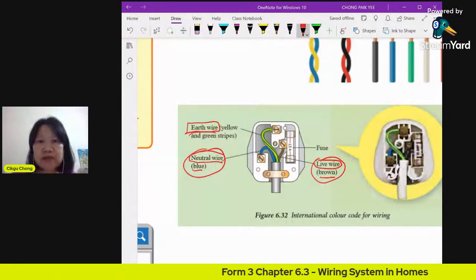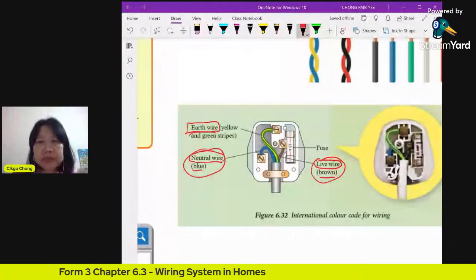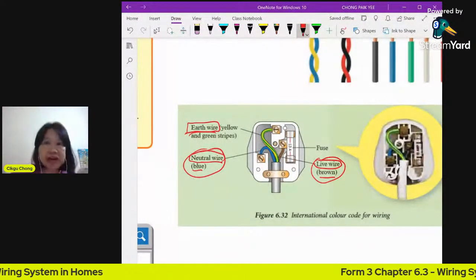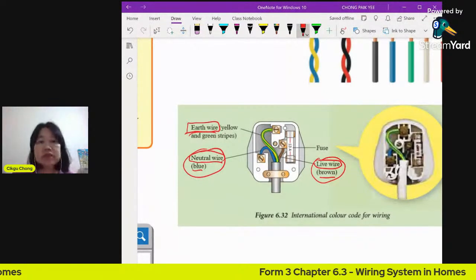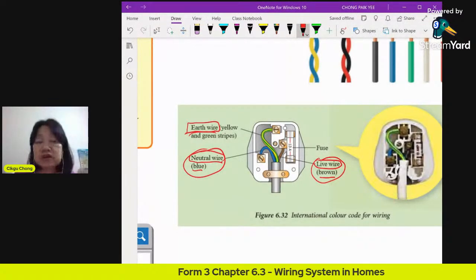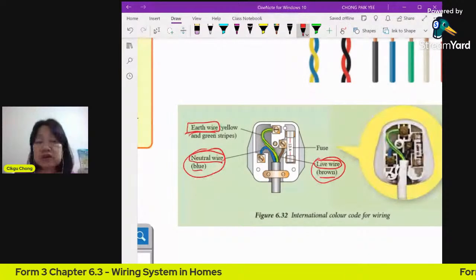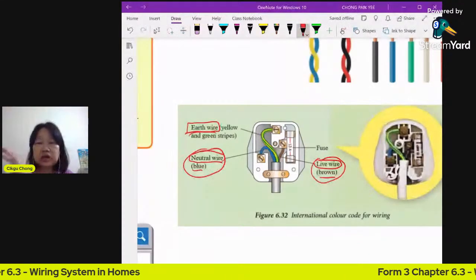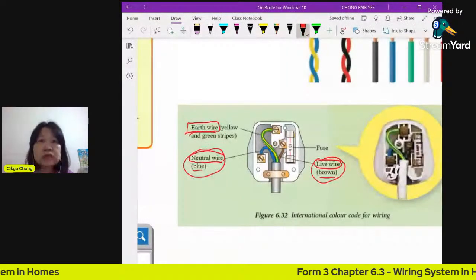It will go into the wires and into the wiring system. If you're touching your iron and ironing during a thunderstorm, and you don't have your earth wire here, the excessive current will flow into the wire, and you're touching it, you may leak, right? And then you will get electrocuted. In order to prevent that, you have an earth wire.